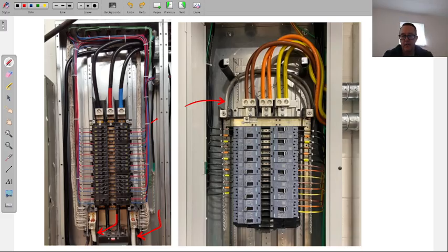One of the things that you will notice, it should translate fairly well on screen, and this is what I mean by a lot of what's going on here. If we look at the 2 different style breakers, and if anything is not clear on screen, let me know. A lot of single pole breakers on this panel, a lot of use for our neutrals in this panel. Lots of neutrals. If you look at my higher voltage 480 volt panel, no single pole breakers.